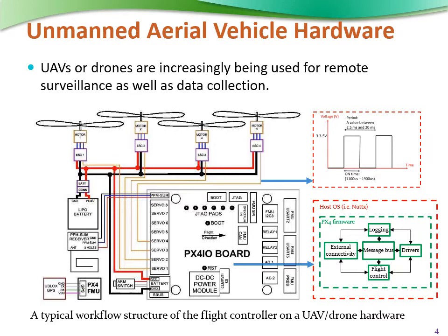The PWM signal, pulse width modulation, controls the speed of the motors through the on and off time of the signal. It controls the average value of the signal, and accordingly the ESC firmware controls the speed of the motors.